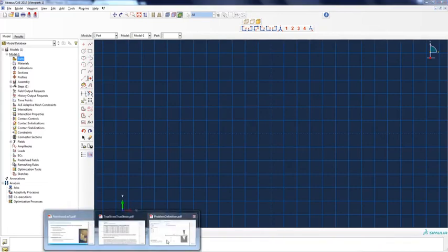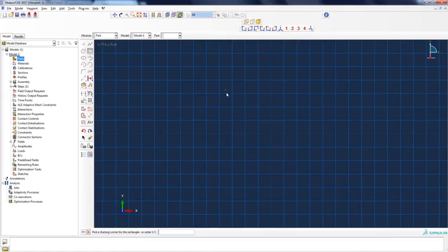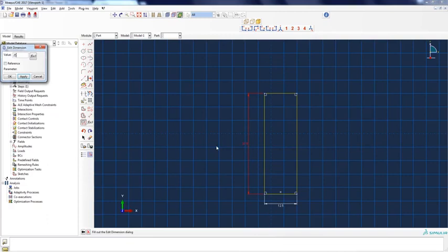And the base, we create only this part. So we have this bottom width being half of L2, which is 12.5. Height is 25. Let's create a rectangle first. Give it a dimension 12.5 and 25. Oops, I accidentally clicked it, enter, so we can modify it. 25.